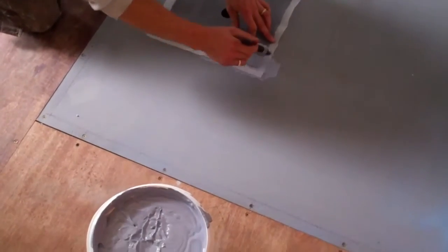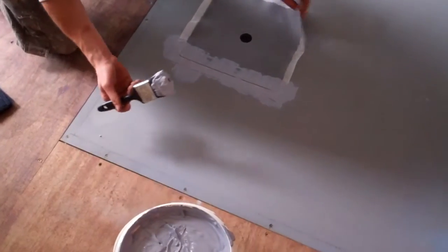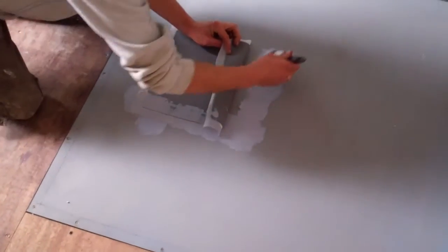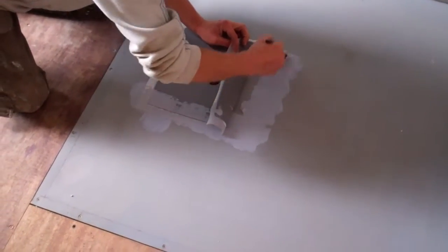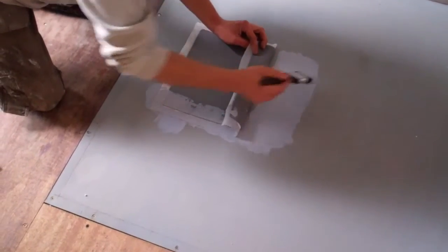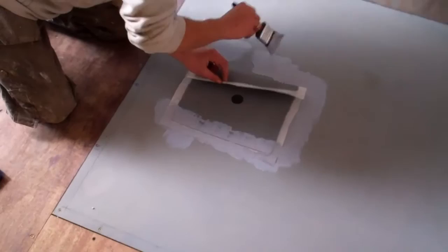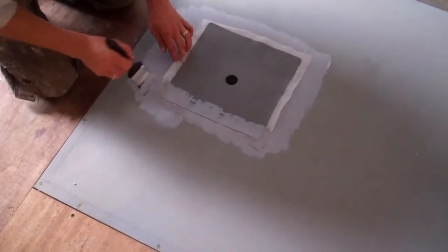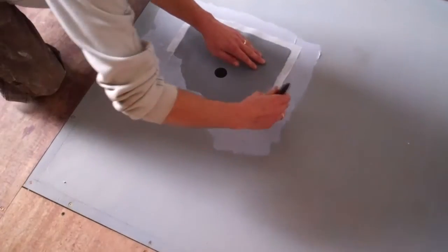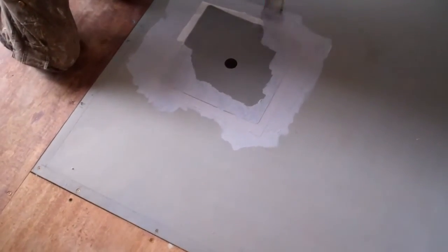Make sure the large sleeve is positioned centrally over the waste outlet. Fold back each side in turn and apply the Aquaproof compound by brush between the back of the sleeve and the shower tray former. The compound should extend under the sleeve by about 5 centimeters. Once all edges of the sleeve are bedded into the fresh compound, we brush more compound 5 centimeters over the sleeve, over the fabric border and a further 5 centimeters onto the shower tray former.